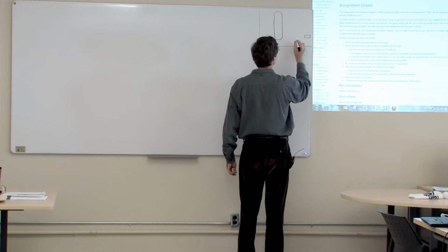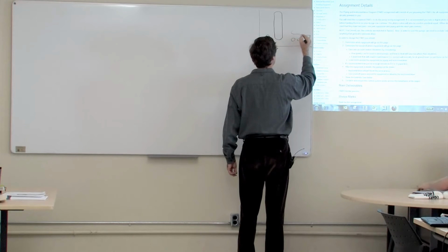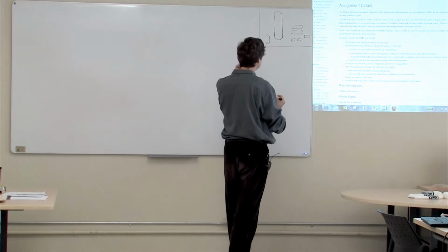I'm going to need some reflux pumps, and they need to sit on the ground, so I'm going to put those here and here. And I need to get my reflux drum in on top of that, roughly like that. And on top of that, I need to put a condenser like that.